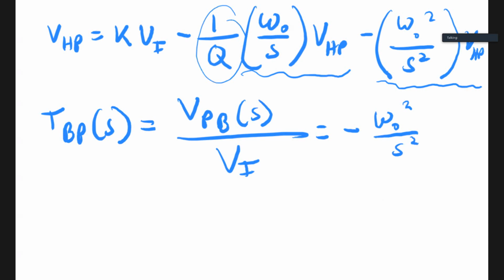Oh, sorry. I don't want to integrate twice because that would make it a low pass. So I only want to remove one zero. So for the band pass, I only remove one zero. So that's why it is the output of the first integrator.